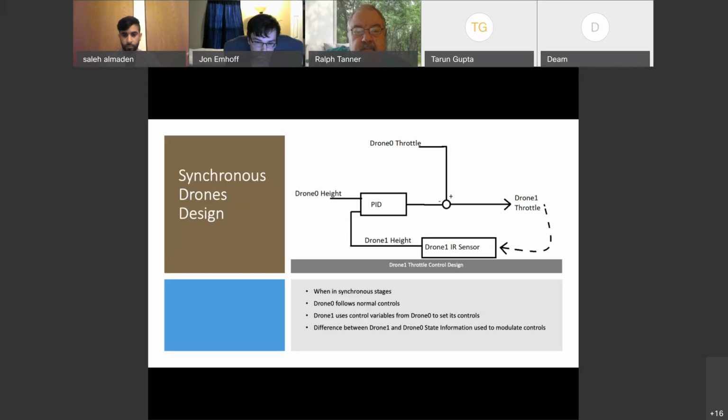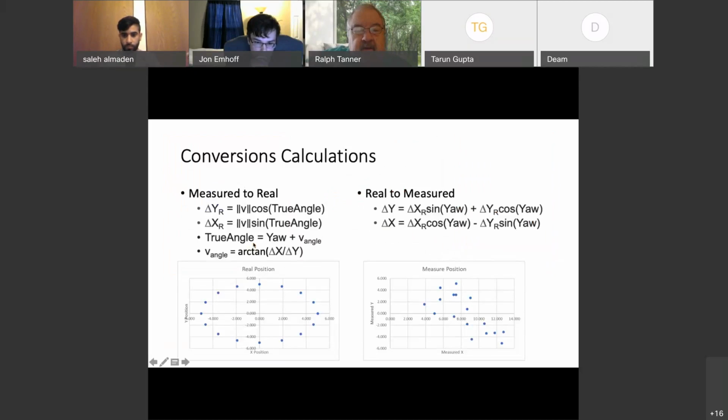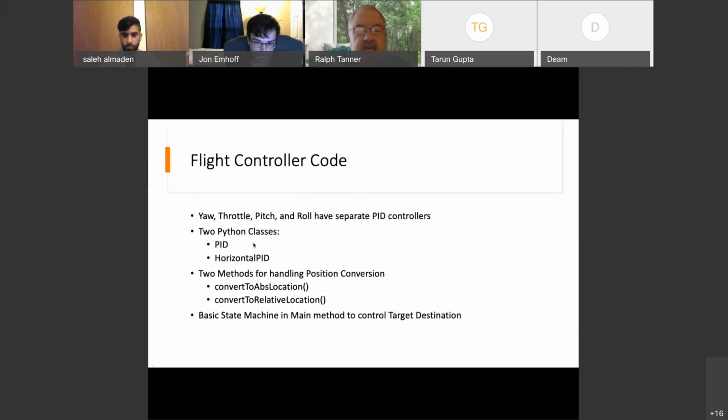So are you talking earlier on? The horizontal PID. Okay, so yes, we had it set so that, for instance, for the X controller, the roll, if the target destination differs from the current position by at least some threshold, say 50 millimeters, then the integral would turn off and reset, and it would be controlled by the KP constant.